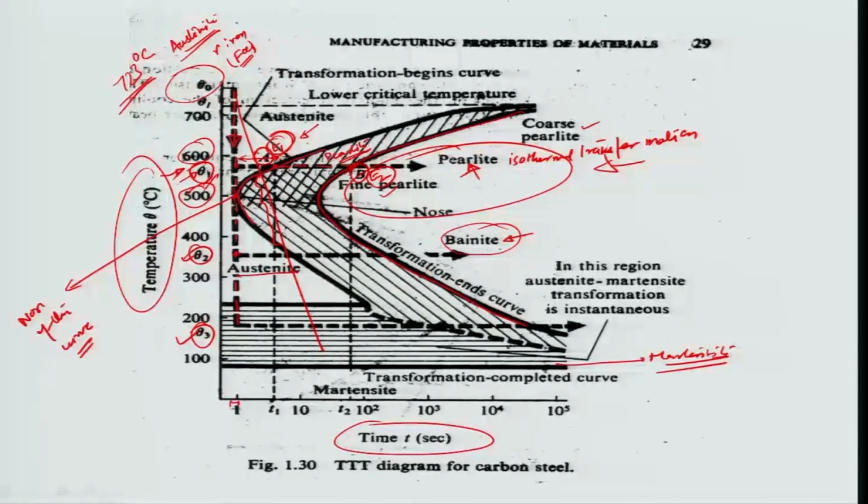Okay. So, beyond this particular thing you have bainite, all this is bainite, and it will not be able to get into the bainite unless it crosses over the pearlite zone, which is here. So, austenite to pearlite to finally bainite, if it is isothermally being transformed as a function of time. So, ultimately you get bainite, but it comes through this zone right here. Okay. So, that is how you interpret from the time temperature transformation curve the various structures based on different time points.